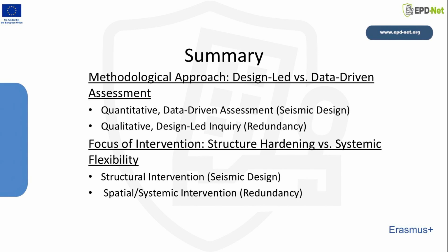It produces quantifiable loss estimations, e.g., probability of building collapse, number of homeless, economic repair costs, that are directly mappable onto a GIS tool. This allows decision-makers to gain a global, statistically representative view of the vulnerability of the old masonry building stock.